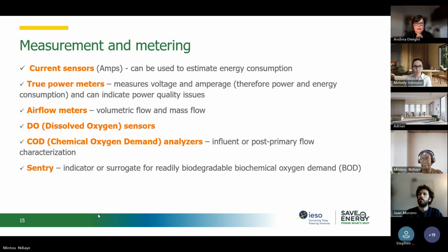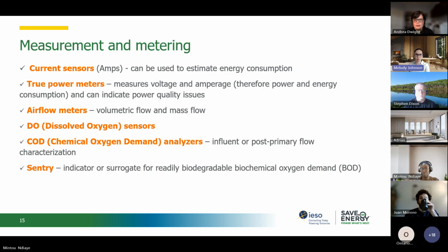Next slide. So now we'll get into some measurement and metering. First to deal with the energy itself. Then we'll look at some process measurement and metering, airflow meters, dissolved oxygen, COD and equivalent BOD as well, to control the aeration system and reduce the energy use. So I'll hand it back to Andrea to discuss the current sensors and power meters.